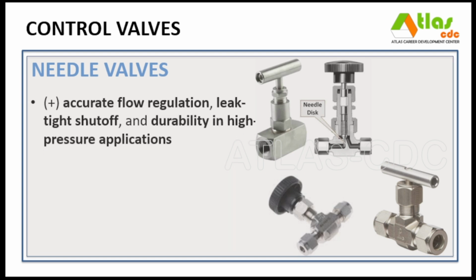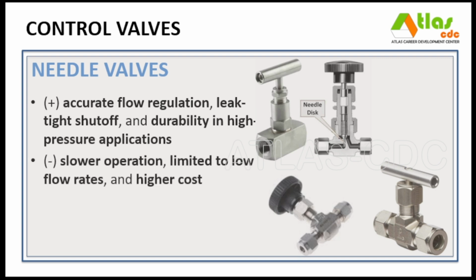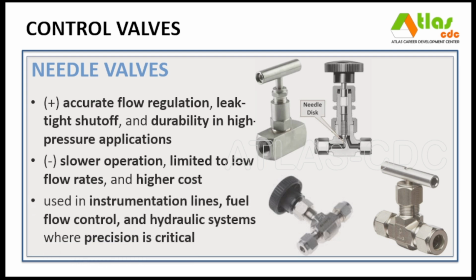Advantages include accurate flow regulation, leak-tight shutoff, and durability in high-pressure applications. However, its disadvantages are slower operation, limited to low flow rates, and higher cost than basic shutoff valves. It is typically used in instrumentation lines, fuel flow control, and hydraulic systems where precision is critical.